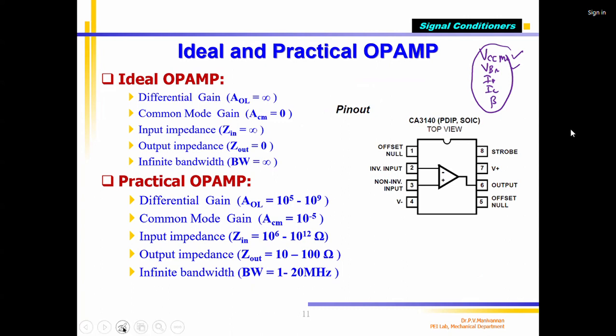Similar to that, in the case of an op-amp also, you are getting a signal. What do you use the amplifier for? I have a thermocouple, for example, a sensor, TC, which measures 0 to 500 degrees centigrade and provides a proportional voltage of 0 to 40 millivolts. This signal needs to be amplified to, for example, 0 to 5 volts, because this signal is very, very low. Per degree change, it will be in microvolts. That voltage cannot be directly given, so you have to amplify it. For that, we can use a transistor as an amplifier, or you can use an op-amp.